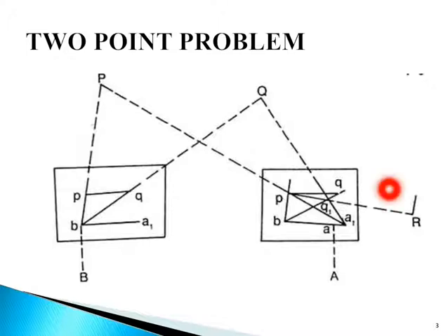Now what we have to do? We have to move the table to the station A, with A1 just over A. So we have to establish the table so that the point A1 comes exactly over the station A. It is labeled and oriented by back sighting, with the alidade touching small p. The point capital P is bisected and a ray is drawn.